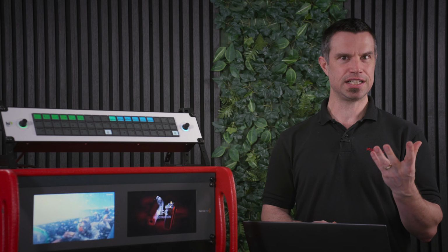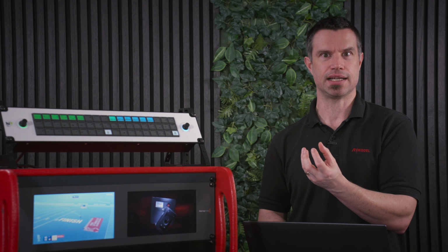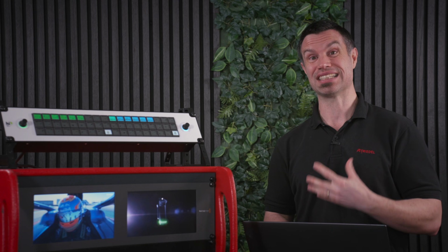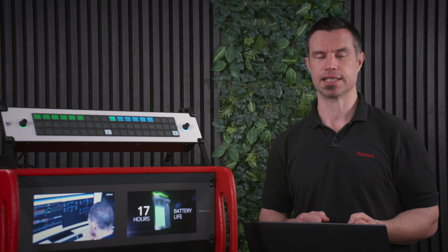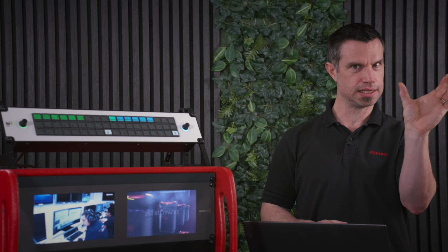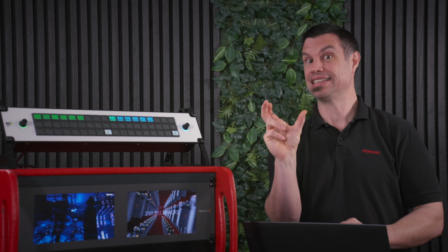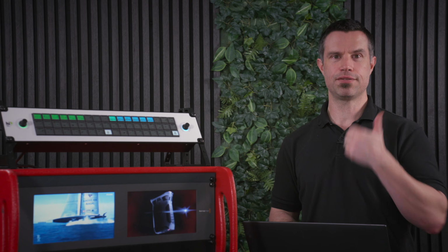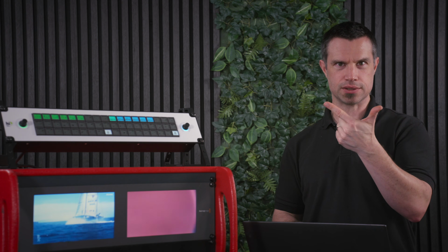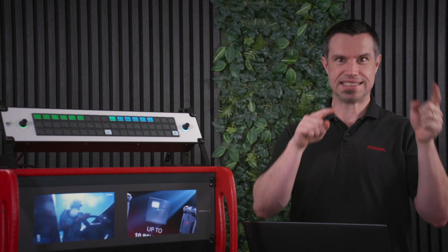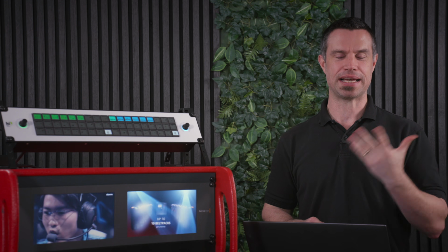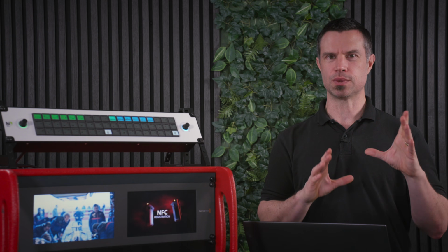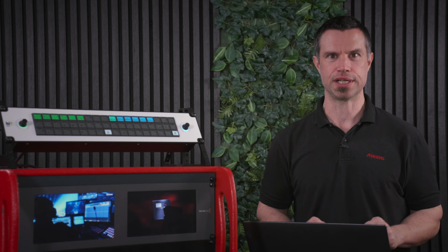Now, when we're dealing with a signal such as an SDI, we have different essences, and inside the control system, that's treated differently as separate signals. So we have the image on one side and the audio on another. And actually inside an SDI signal, we have 16 audio signals, not just the one. If we have the image and the 16 audio channels together, then we could do 17 different operations every time we want to patch them, but it's much easier if we can do one, if we know that we always want to move the image with its 16 audio channels.